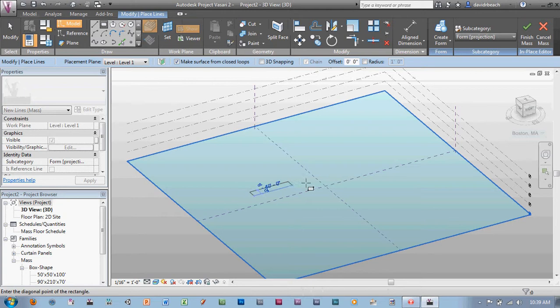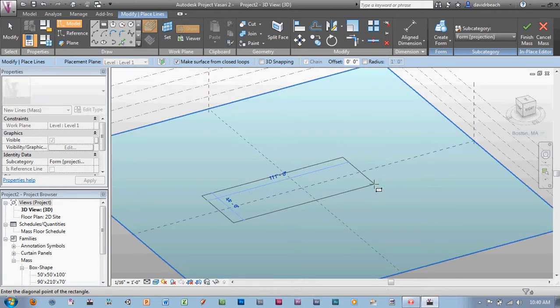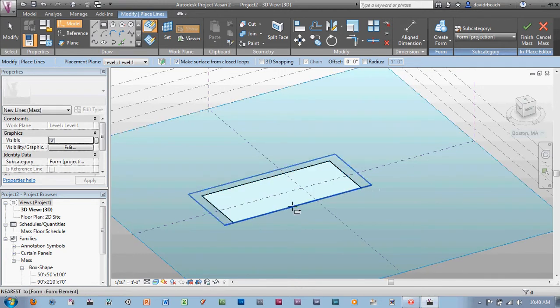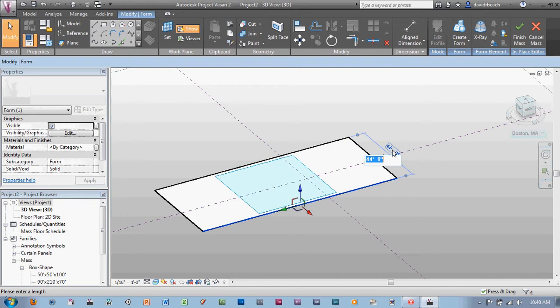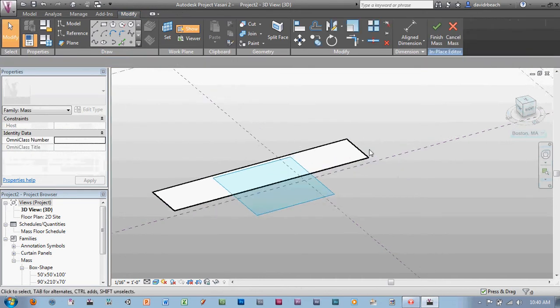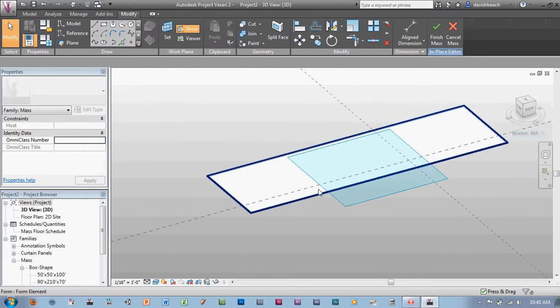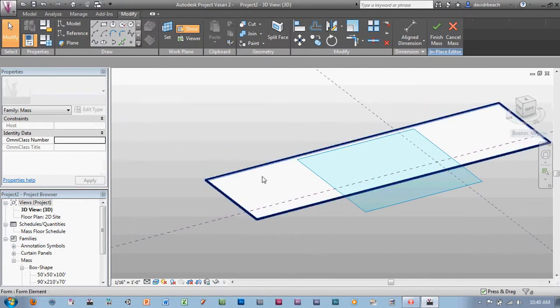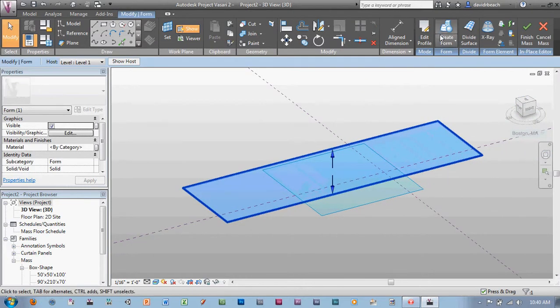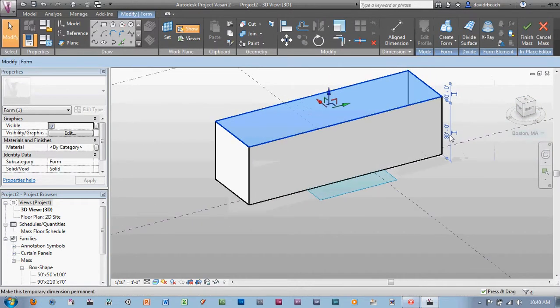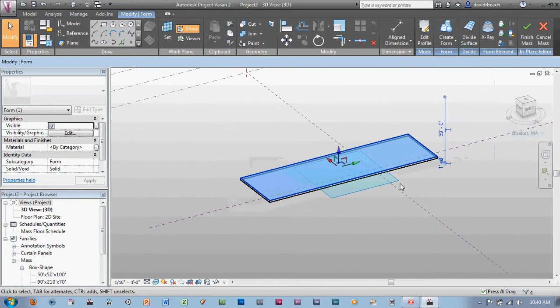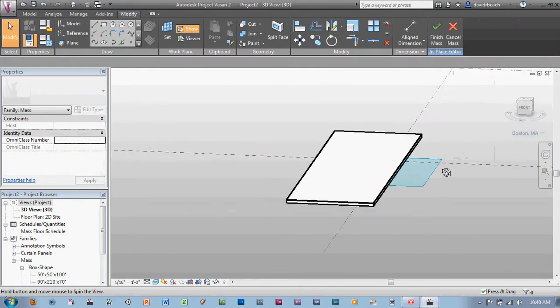The first thing I'm going to do is build a base. If I'm working with the Ripley project, for instance, I'm just going to ballpark some things here, about 100 feet by about 20 feet in size. Let's make that 30 feet. Now, what I want to do is quickly mass out a section that we can run wind through. So I'm going to give this base about a 1 foot height, because again, I need a surface on all 6 sides to guide the wind through.